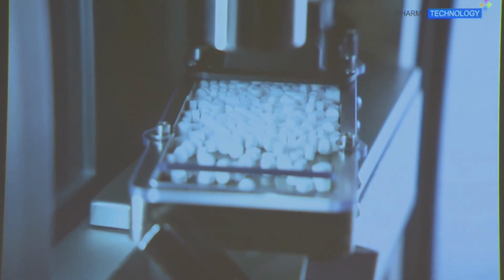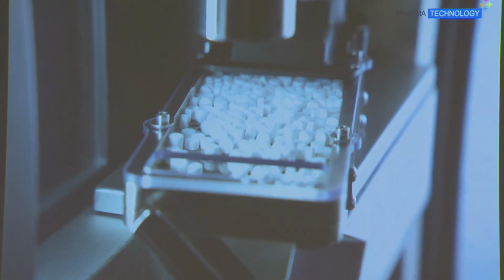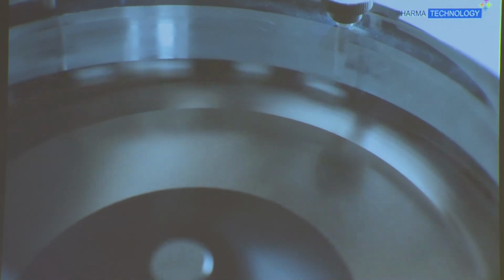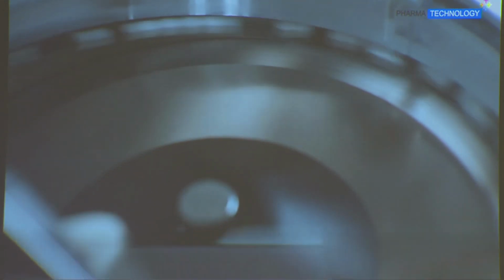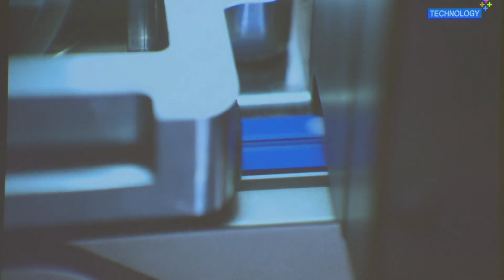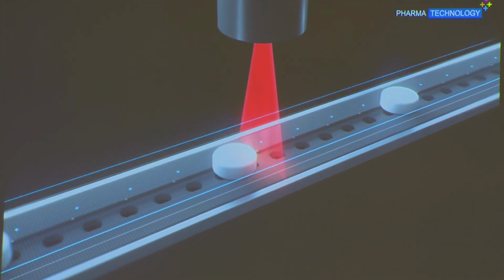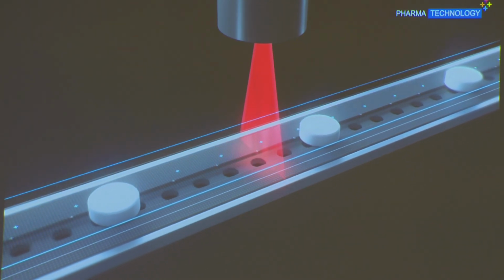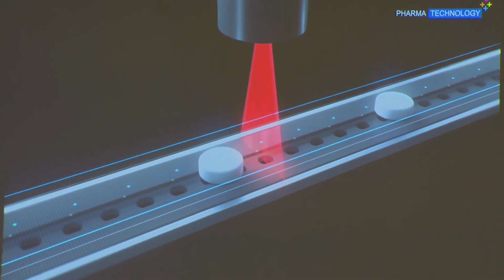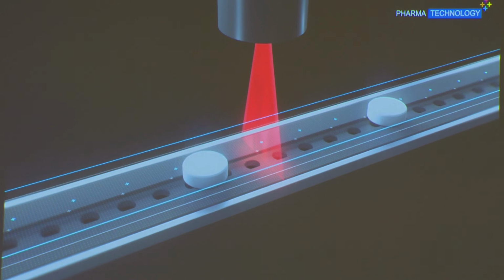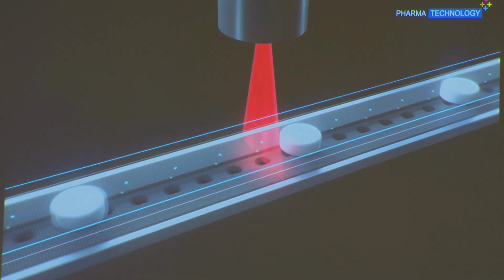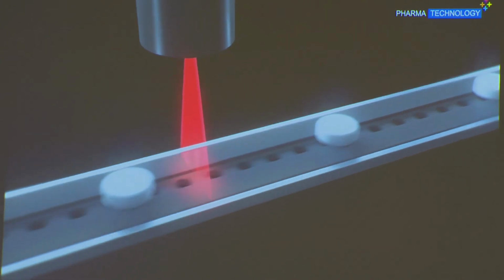First, the vibrating pre-feeder receives tablets from the hopper and doses them into the centrifugal bowl. From there, the tablets are aligned and distributed one by one on the conveyor belt. The fixed speed vacuumed conveyor holds the tablets in perfect position and brings them to the 3D laser scanner. This 3D laser scanner verifies the exact position of the tablets and informs the NIR probe in real time to trigger the spectral acquisition with high accuracy. At the same time, the thickness and diameter are measured for each single tablet with an accuracy of 0.1 mm.